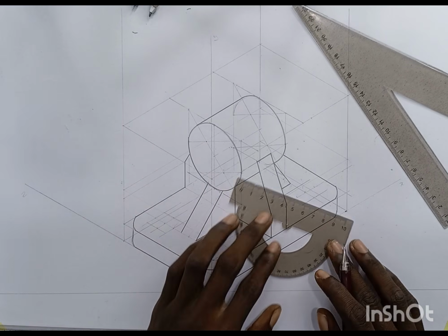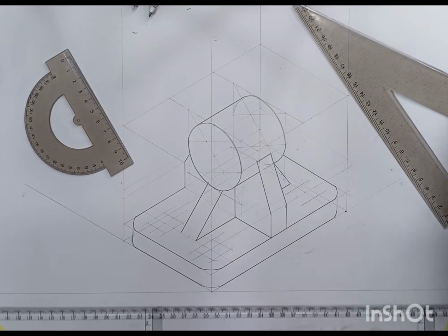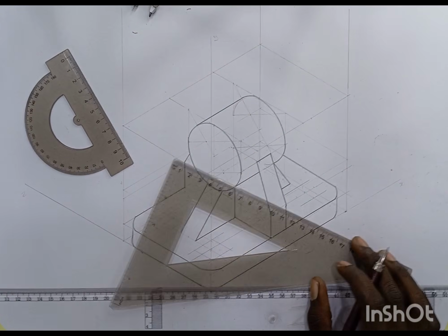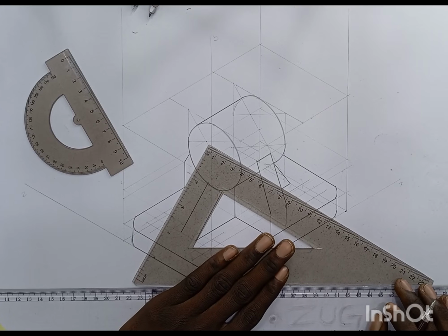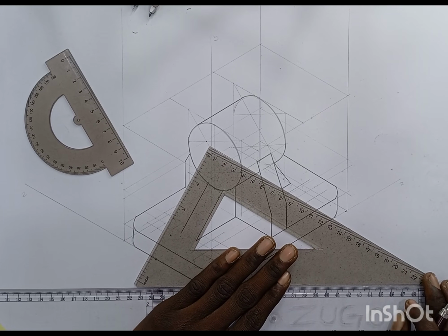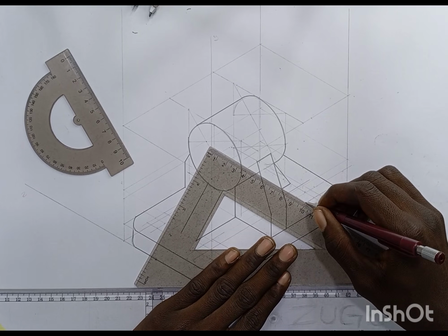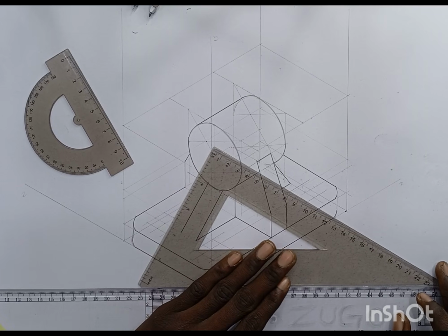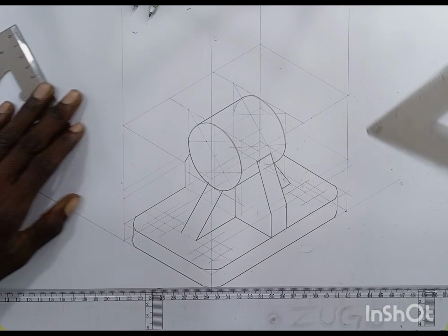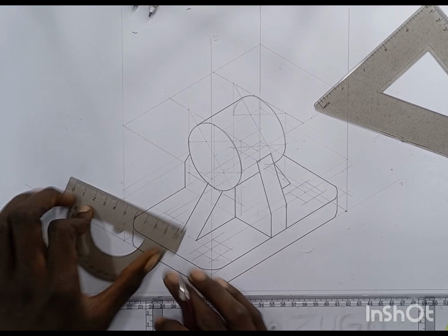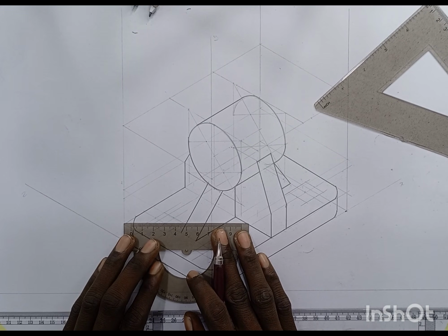Okay, so I'll do the same thing for this one also. For this, let me use the set square. So if you want to use the set square, you don't need to make 2 points. You can just use 1 point. Across the 30 degrees, you can just cut. It's going to be a parallel line. But if you don't have an accurate 30, 60, 90 set square, it's going to give you a wrong value. So now, let's have a diagonal here.